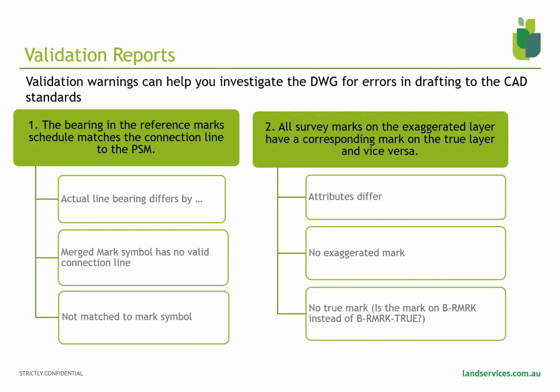Validation reports can help you catch drafting issues early. The CAD and PPR validation reports flag warnings in your DWG that relate directly to the CAD standard, and some of those warnings will also show up as errors in the closures report, requiring overrides and acknowledgements.